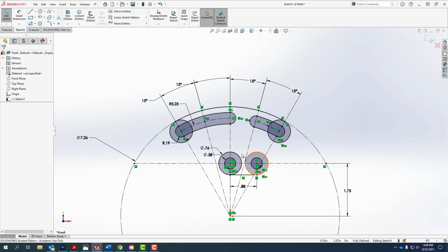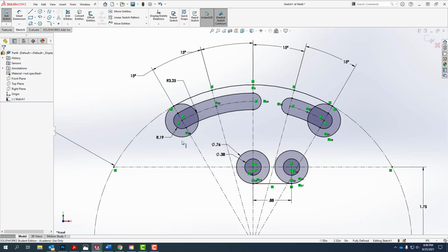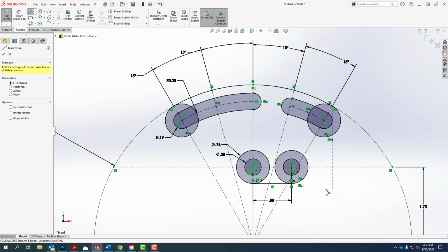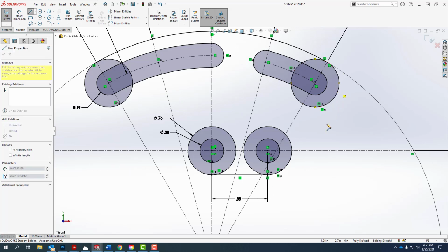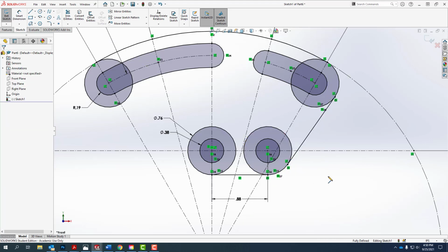Now I have two more lines to put in. I have, or rather, the curve here. So it's a straight line over, there's a fillet and a straight line, and a straight line over here. So let's do the right hand side. We know that we have a tangency. So as I showed before, we're going to click and drag, make sure we have a tangent there. Just come over to the circle and left click when the line jumps to being coincident and tangent.